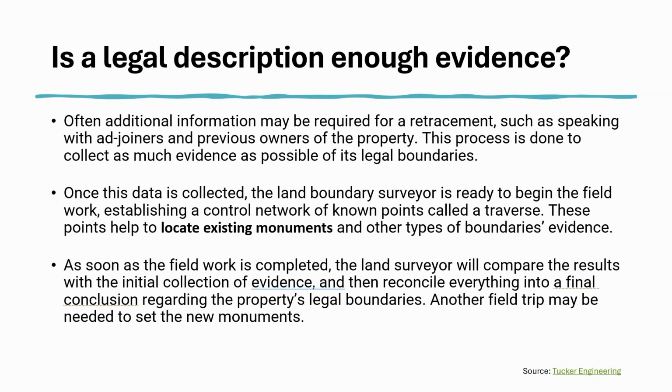If you can't find it, potentially set that new monumentation. And again, that's where a lot of times pincushions can happen. Original monumentation's lost, so a surveyor goes out and opts to set their own because they didn't find the original one, even though there are other pins already set.